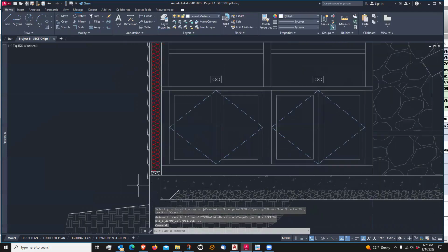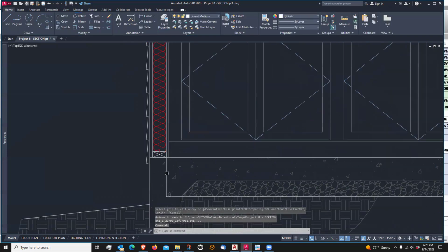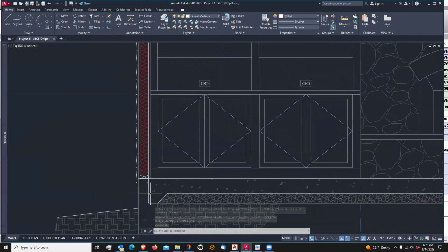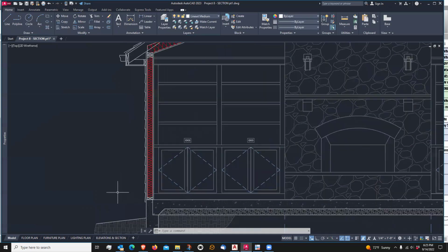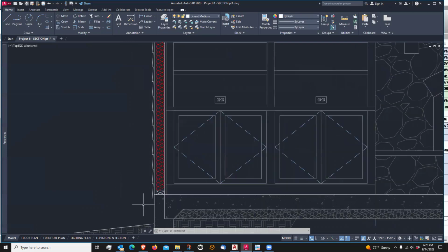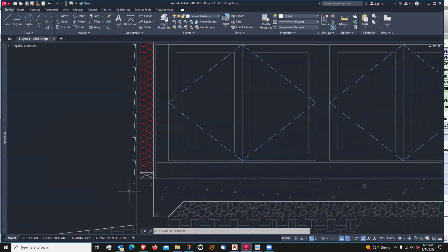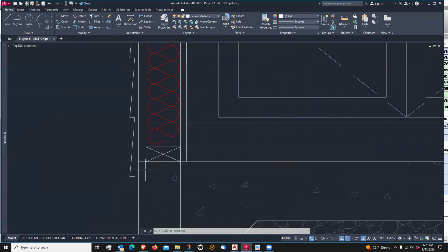Okay, yeah. So in this case, all of our walls are the same height, but if you're ever doing a section, or if you are going to put siding on someone's house, which very well might happen, you need to remember that the last slat, or the last piece of siding, this one right down here, needs to go below the floor line.